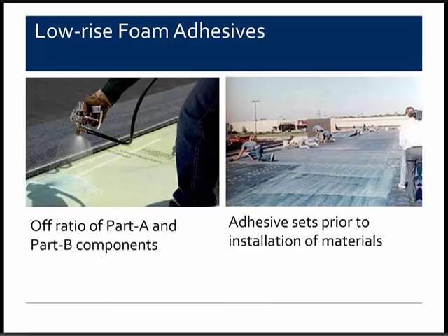You can have off ratio of the Part A and Part B components depending on the dispensing mechanisms. The gentleman on the left has a spray nozzle that probably has some kind of temperature range where it allows the A and B components to mix properly and dispense out the gun tip.